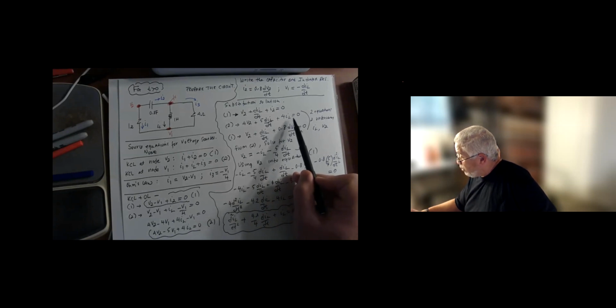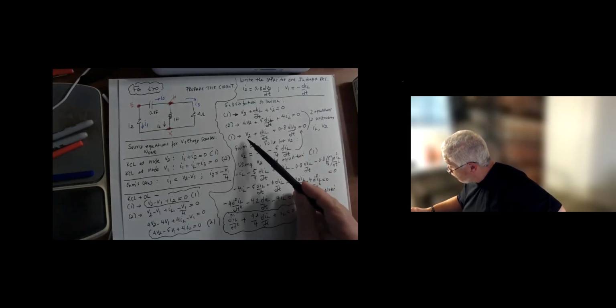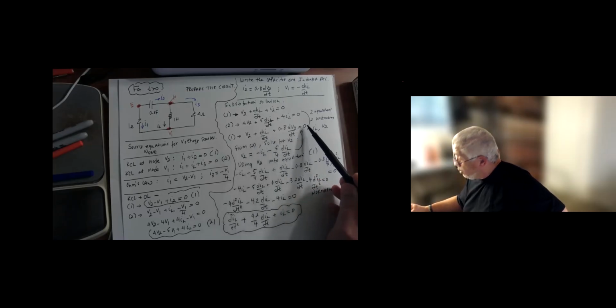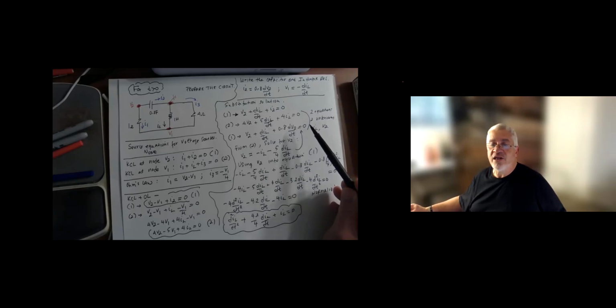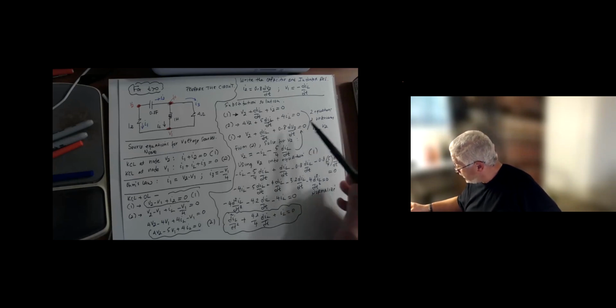At this point, I use the capacitor relationship, meaning wherever I have I2, which is only in equation 1, I put 0.8 dV2/dt. So for equation 1, you get V2 plus dIL/dt plus 0.8 dV2/dt equal to 0. You should pause and check whether you have a system of two equations with two unknowns. The unknowns are V2 and IL.